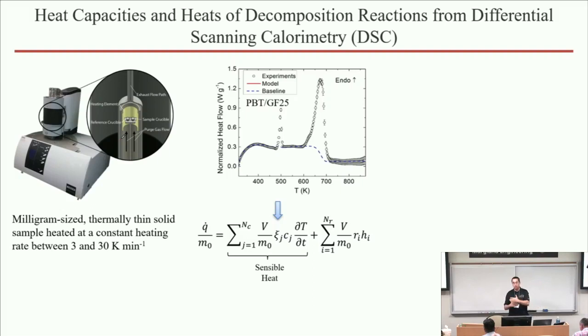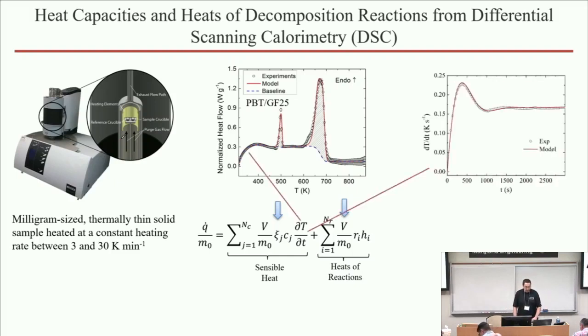So we use the thermal decomposition data to simulate this baseline curve. We can adjust the heat capacities of our reactants and products to match the results, and now we have the information about these heat capacities. Now we can integrate the corresponding peaks, and we can extract the heats of reaction and corresponding heats of melting. We tie it all together. We are very careful here.